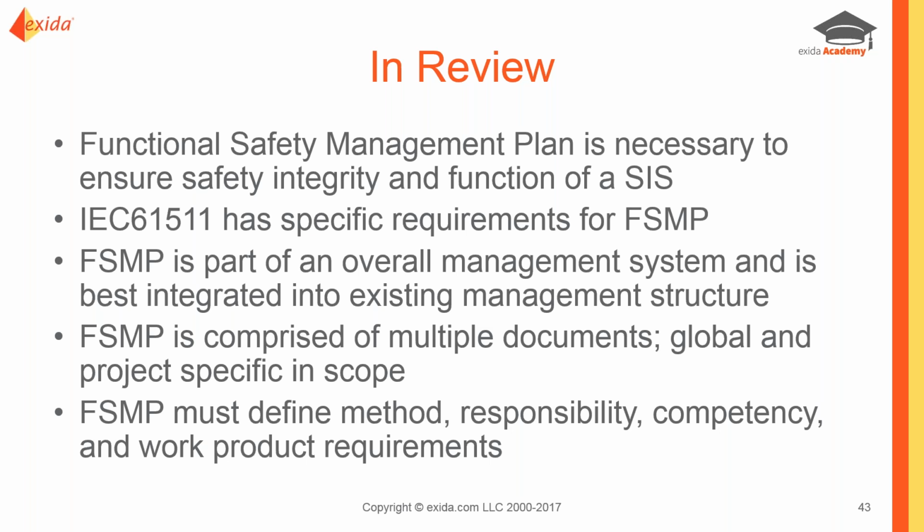IEC 61511 has specific requirements for what goes into that functional safety management plan. They are performance-based requirements, so there's interpretation that individuals can apply to your individual situation. We do want this FSMP to be part of an overall management system and integrated into the best practices of an organization. It involves a lot of documents. Some are global in scope, some are very project-specific or SIF-specific in scope. The document needs to suit the purpose of that scope.